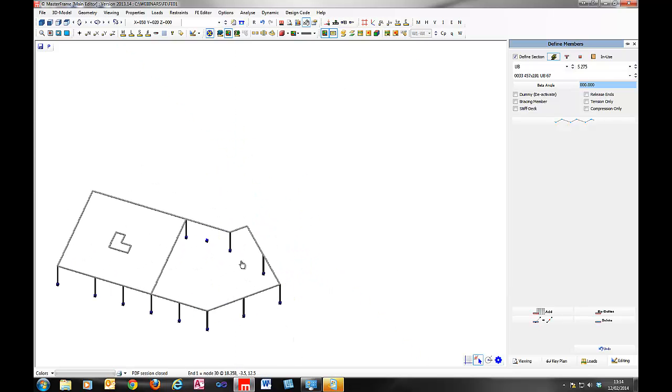And an interesting thing I can do here to introduce some intermediate columns is if I hover my mouse over these 2 points to create temporary tracking points, because that's a temporary tracking point, I get tracking lines at all the members which are aligned with or perpendicular to that member. So I'm going to go with a line perpendicular to the member here, and as I approach this tracking point, just to reintroduce that, it also has a perpendicular line to one of the members it's associated with, so I get a point of intersection automatically occurring there, again allowing me to put that column in precisely where I want it to be.